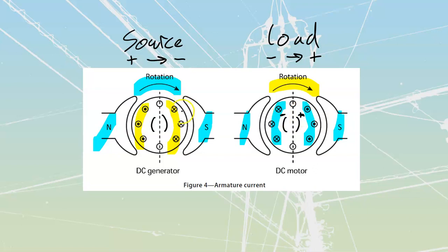If we take a look at this, current flows from positive to negative. My current is flowing through in that side, which means I would have a positive here and a negative over here. They're showing that for the same polarity, positive, negative, off the commutator, we're going to have actually opposite directions of current inside here. But they are opposite machines, so this just makes sense. One is taking in electricity to create rotary motion. The other one is providing rotary motion to create that electricity.